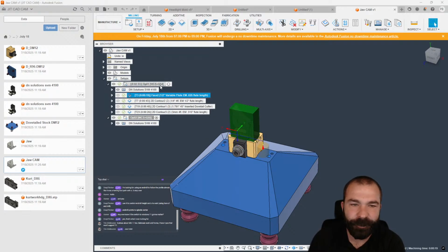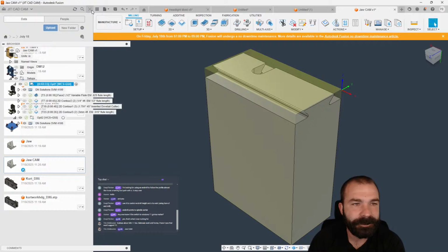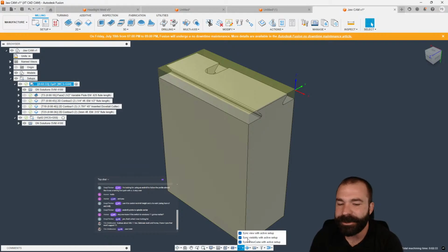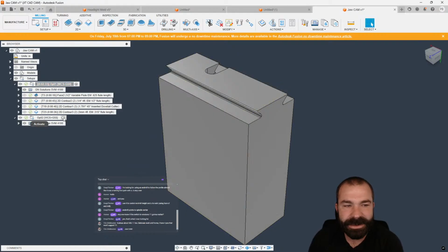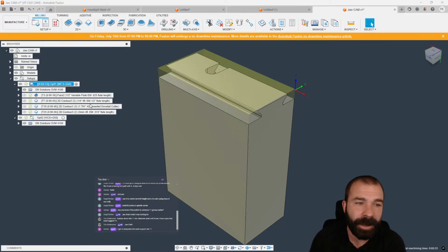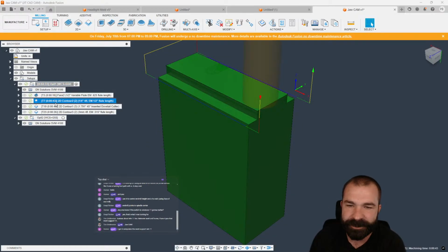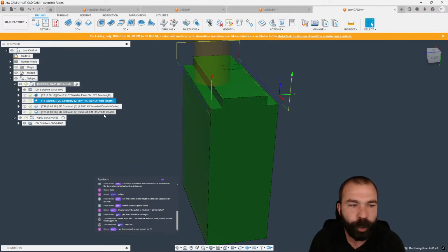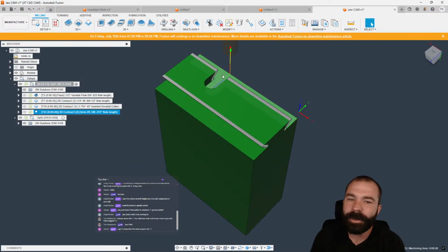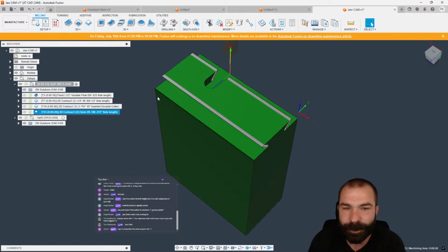So what they've done so far, if we go ahead and activate this, again, super neat pro tip: down here at the bottom, you have this little yin-yang circle. Go ahead and synchronize all your views, because as you will see me do here today, anytime I activate a setup, I can quickly jump between things and it turns everything on and off. As you're seeing here, great system they're using. Dovetail setup. They're cutting everything out, and then they are using a dovetail system with a pin alignment.